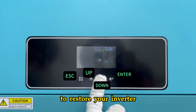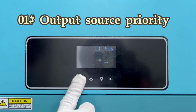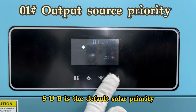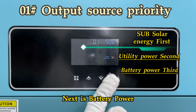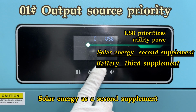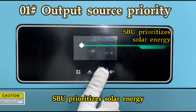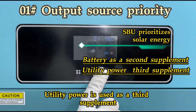To restore your inverter. Setting item 1 is for setting the output power priority. S is solar energy, U is utility power, B is battery power. SUB is the default solar priority. Utility power is used as a second supplement. Next is battery power. USB prioritizes utility power. Solar energy as a second supplement. Battery used as a third supplement. SBU prioritizes solar energy. Battery power is used as a second supplement. Utility power is used as a third supplement.